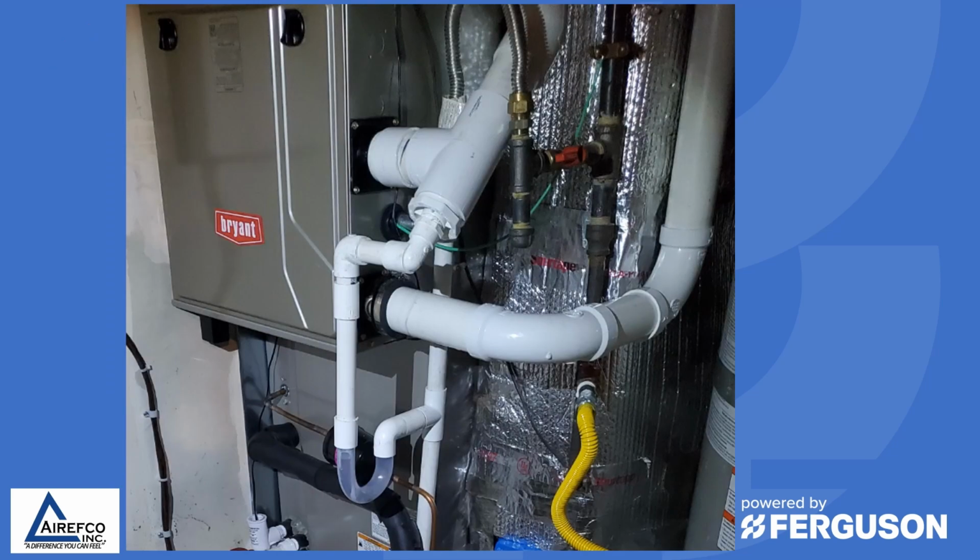A number of years ago, I was invited to a fire inspection where a gas furnace was being suspected of starting a fire in a home. And the inspectors there were taking a lot of pictures and gathering evidence to try to figure out why the furnace had started the fire. When they inspected the furnace, they found that there was no drip leg on the gas line going into the furnace. Even though this probably would not cause a fire, it was a center of concern for the inspectors because NFPA requires a drip leg to be put into a gas line supplying a gas furnace.